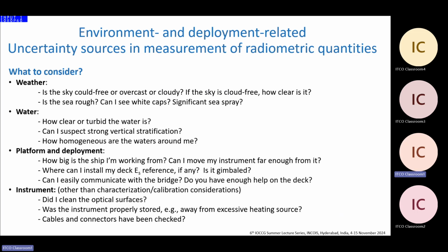Maybe I forgot to clean the optical surface, so I should keep this in mind. Was the instrument properly stored? You don't want, as Matt said, to leave it on the deck for hours under a big sun. It's going to warm, and then you don't know what the response is going to be. You might even damage your instrument. Did you check all your cables and connectors? And the list goes on of all these things that you have to consider.